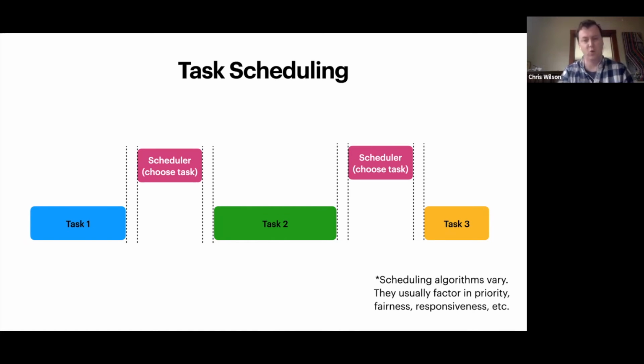Just to not overload words, I didn't call these threads, but you could think of these as threads of work, where you have different tasks that you want to, quote unquote, all run at the same time. But in reality, you're running a scheduler periodically, and depending on various priorities or what you need to get done, or maybe just round robin, one after the other, you stop that task, load up a different task, start doing that for a little while, and then hop over to the scheduler again and continue.